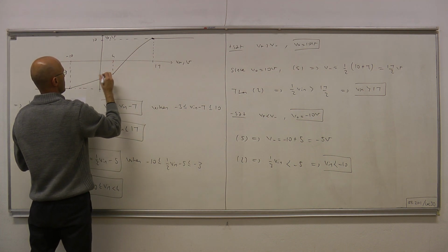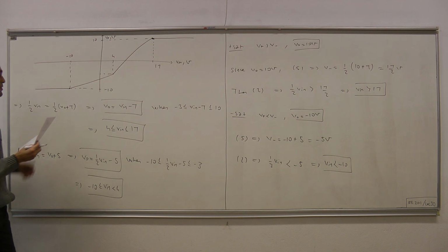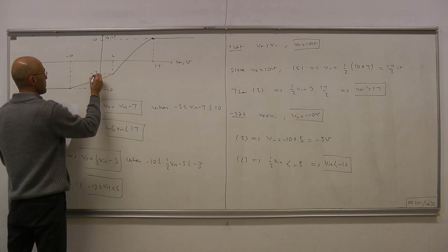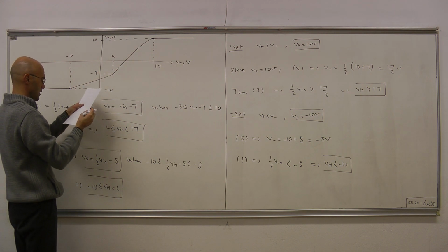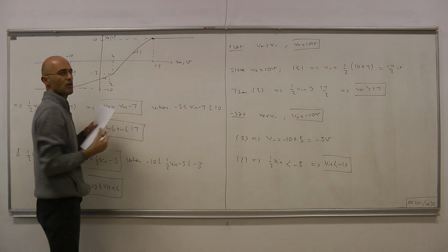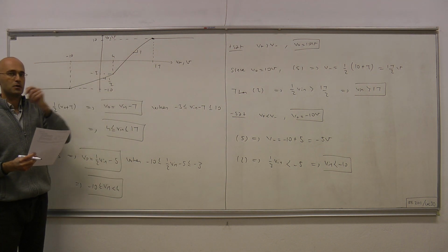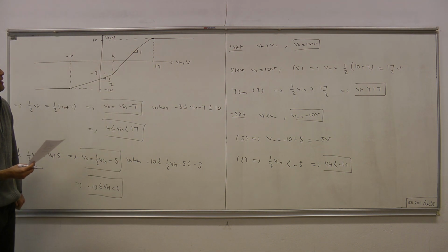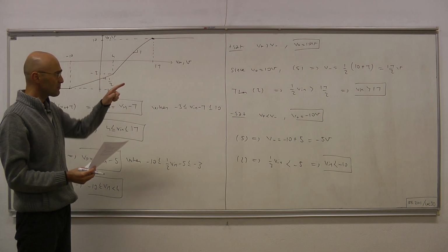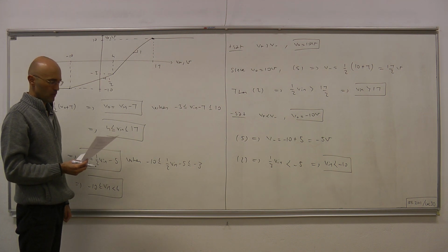So here we have a breakpoint in the middle of the linear region. The corresponding point is -3. Okay. The slope is 1/2, and here the slope is 1. And that's the input voltage, output voltage characteristics of the circuit, which had a piecewise linear component in its feedback loop.